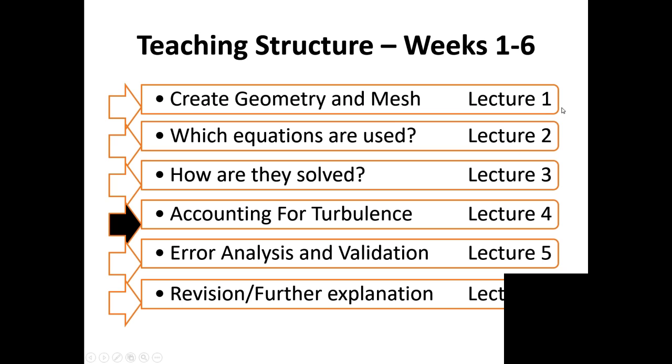Regarding the assignment, the different students asked various questions, so I'll summarize some of them. The basic exercise is for you to do a simple pipe flow simulation, just like in your tutorial. Use a fluid of your choice. Don't take a non-Newtonian fluid or a complex one. Just use something like air, water, or an oil.